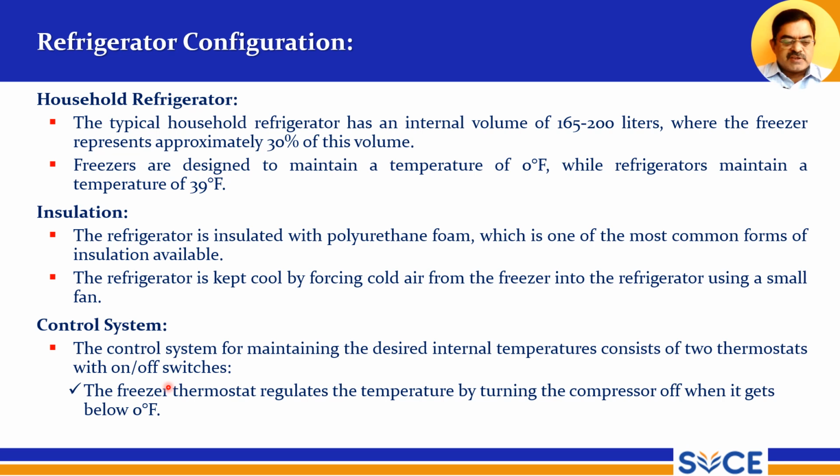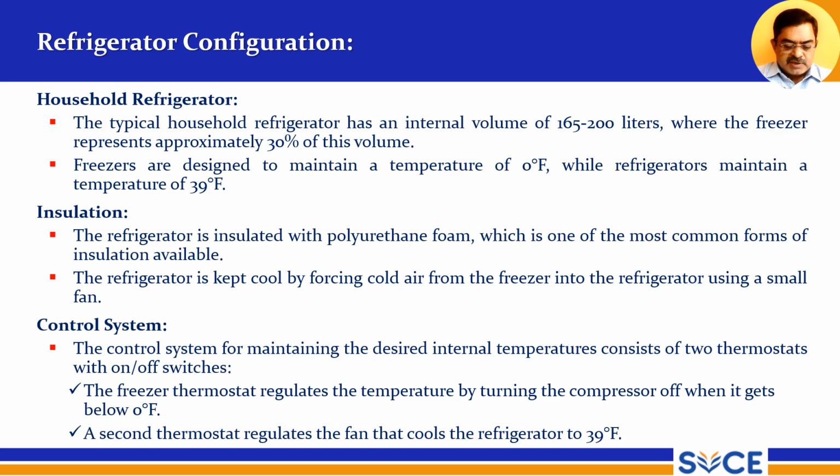The freezer thermostat regulates the temperature by turning the compressor off, which allows the temperature to go below 0 degrees Fahrenheit. The second thermostat regulates the fan that cools the refrigerator to 39 degrees Fahrenheit.